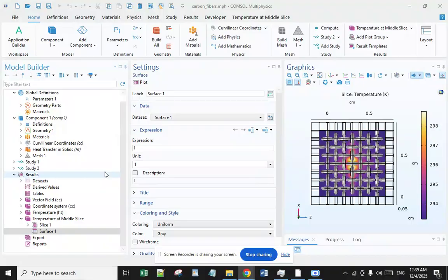thermal diffusivity and conductivity. They determined that thermal conductivity parallel to the fibers of a non-crimp stitch-bonded fabric agrees well with the theoretical value calculated employing the rule of mixtures. The presence of voids due to the yarn crossover regions in woven fabrics leads to a reduced value of transverse thermal conductivity, especially in the single pillar measurements of this study.